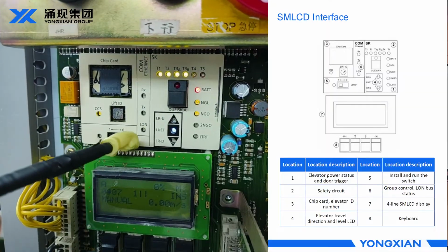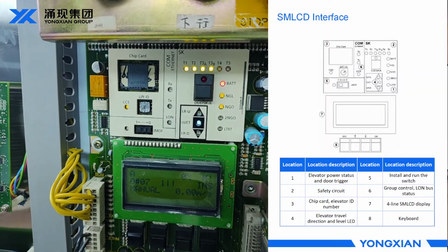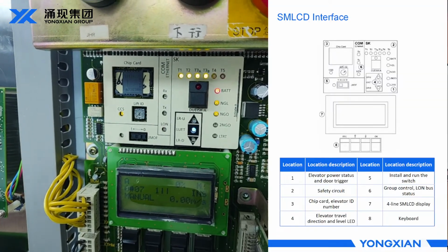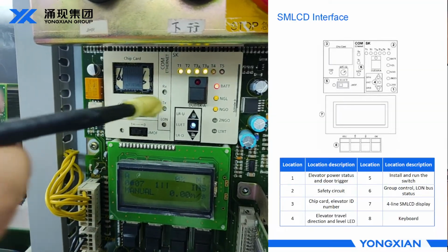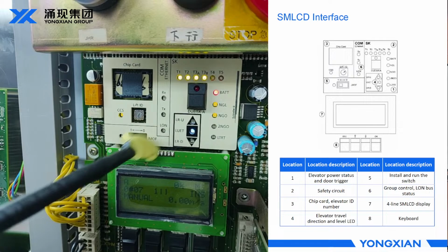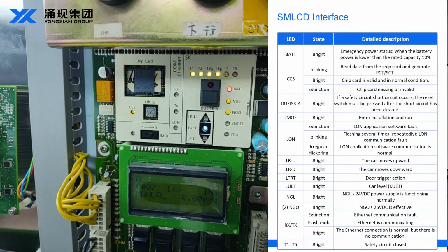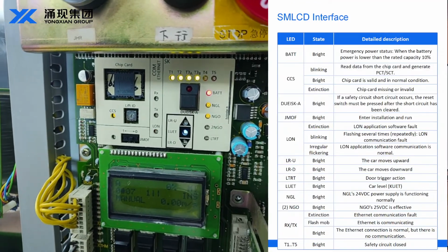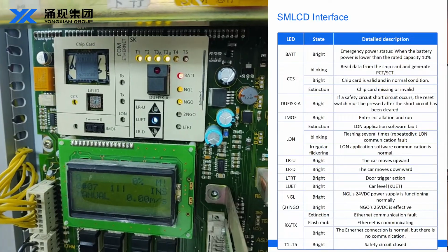Below this is our installation operation mode. And section 5 is the GMOF. It means the job mounted operation function. When the elevator is newly installed, we can change the switch from 0 to 1 to select the installation mode. So when the elevator is under installation, you can change this switch to be on the one side.